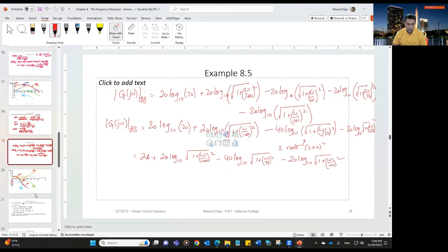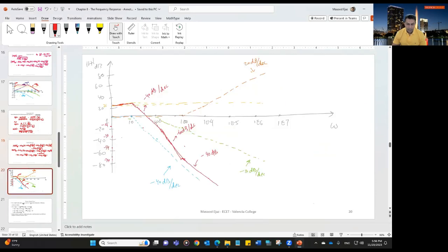The dotted lines. So 2 dotted lines are going to be overlapping with each other, which will be 10, and then the slope is going to be 20 decibel per decade. And then there will be another line, the same line on top of that. So you will see that in my first output example. But when you add all of them together, it will still give you the correct Bode plot. If you do up to that point, then you get basically 80% of the points.